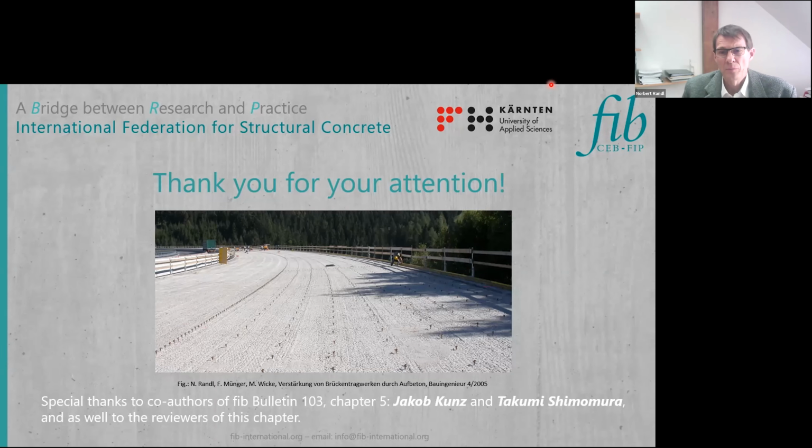Thank you. It's also an important question. You always have to check the quality of the substrate concrete. It makes no sense to place an overlay on a highly deteriorated concrete substrate.